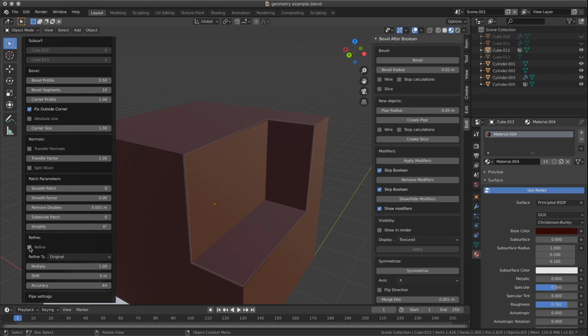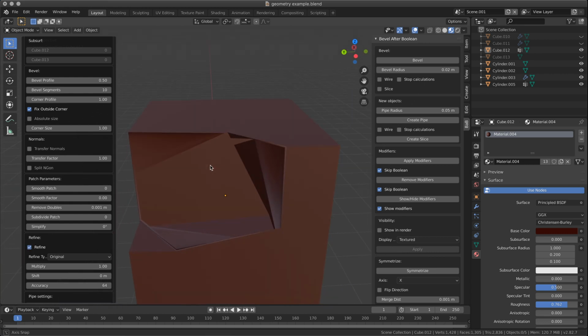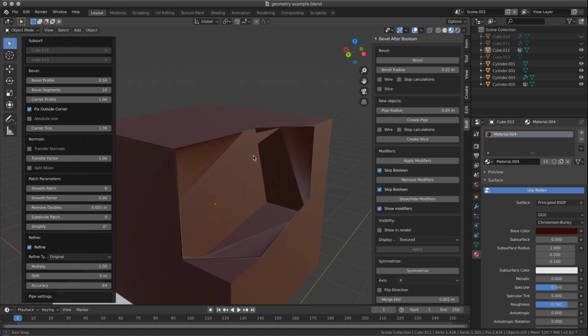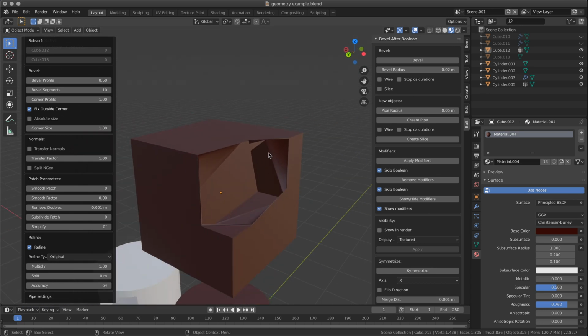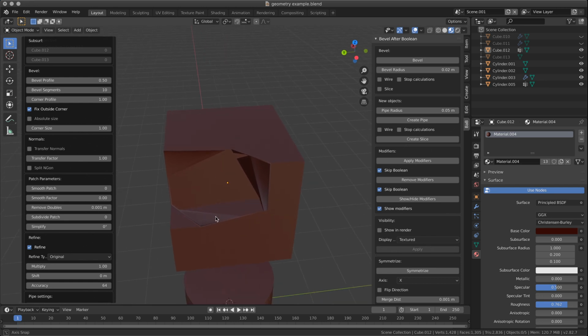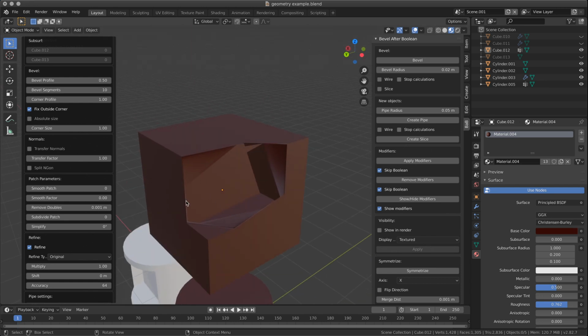I don't know why it was selected, because the two times I tested it, it gave bad results. It's probably good when you have a lot of subdivision, but usually when you're doing hard surface in a non-destructive way, or you need a quick bevel, you don't have a lot of geometry, so by default it should be unselected for hard surface.